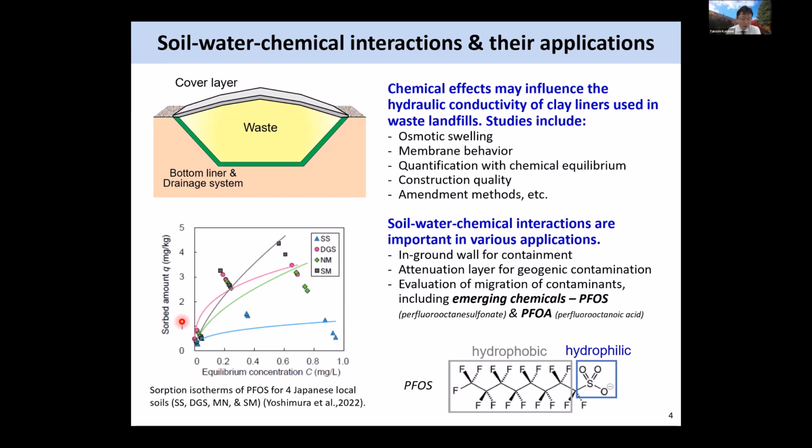It's too late. We have produced and distributed it to the environment already. So the issue is to understand the behavior of PFOS, where PFOS exists. If the sorption is strong in the specific soil, we should attack the soil, like soil excavation or soil purification by using some chemical method. But if the sorption capacity of the soil is not strong, we have to look at the surrounding, the downstream groundwater, whether our PFOS has reached very far downstream and affects the drinking groundwater or not.